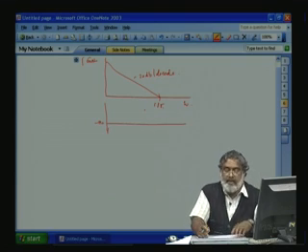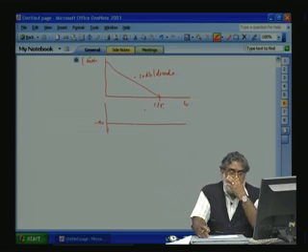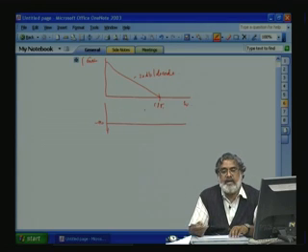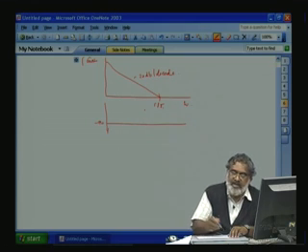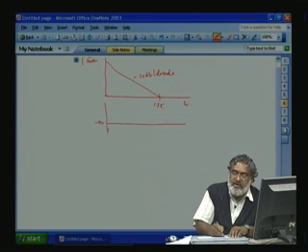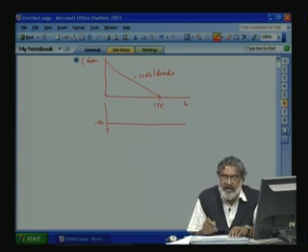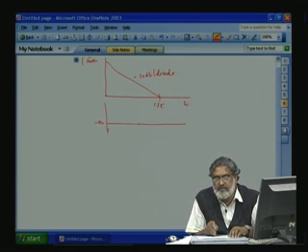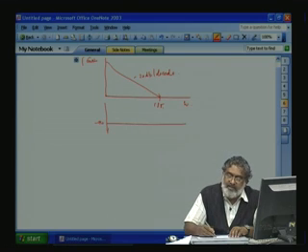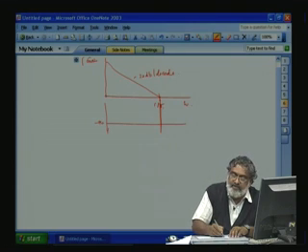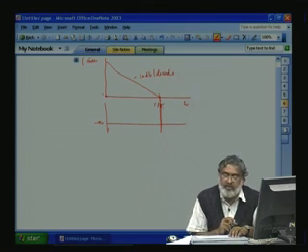So, let us take the PI controller. So, what we want is a controller where a large gain should be possible for steady state error. That means steady state error means for the DC component we should have very large gain. At the same time, we should be able to fix the margin at the zero crossover frequency, where the gain will be 1 on the log scale.